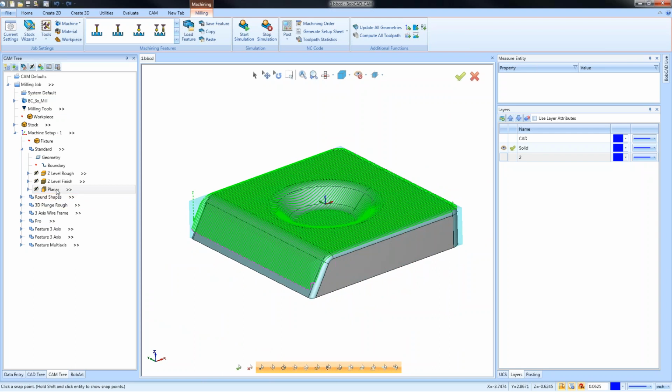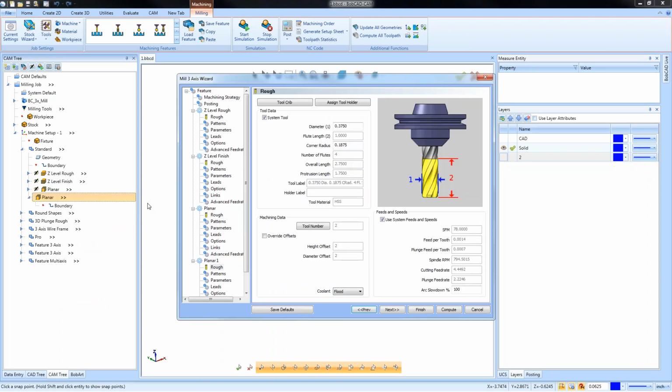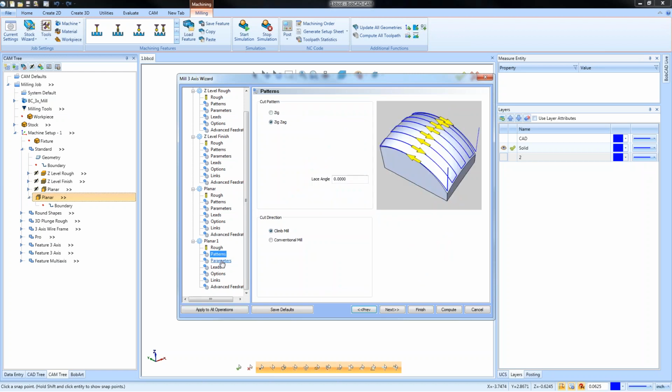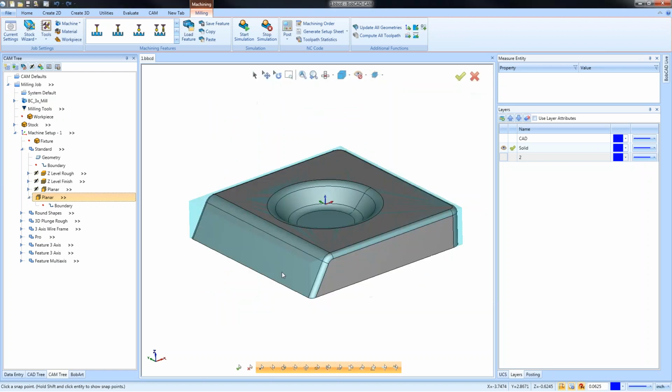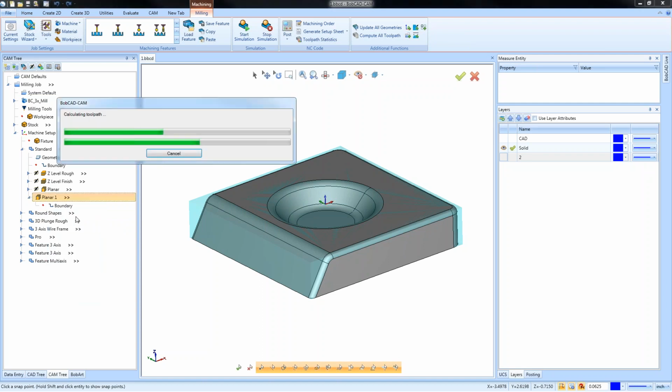Now, you do have the ability to copy these machining strategies, or this operation. So I can copy this operation and I can paste it, all right? And then this gives me the ability to iterate on that toolpath. And I do think when you're learning and testing and trying, it makes sense to make some copies and then make some adjustments and see the difference, right?